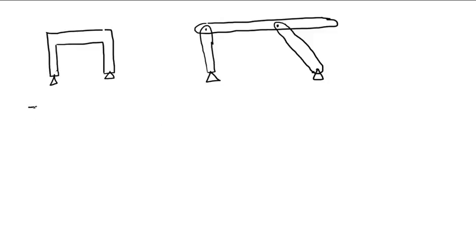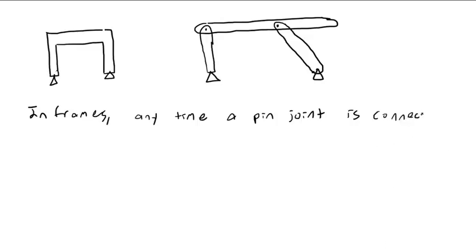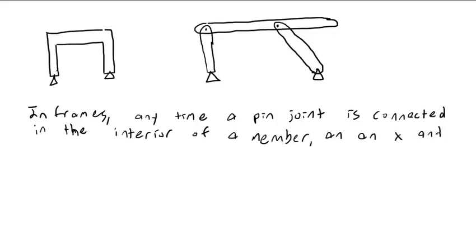So the way you handle this in frames: anytime a pin joint is applied, or is connected, I should say, in the middle of the member, the interior of a member, an X and Y internal force will be applied. Okay.